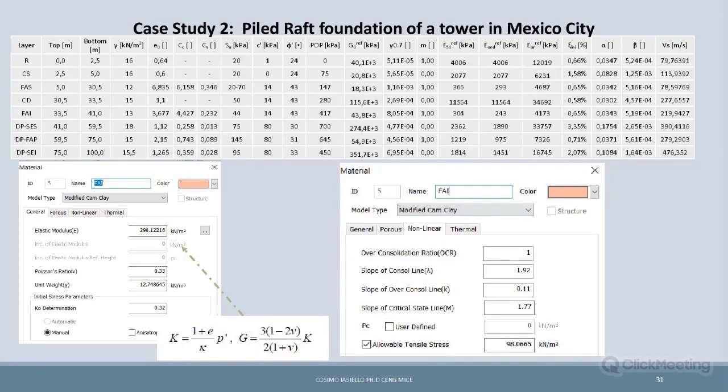Here, what we had at the end of the day was an oedometer test and the CC and CS to evaluate the value, the possibility of the soil expanding or reducing in volume. And then we also have some tests for the Young's models. And with this we could create this table with all of these parameters.